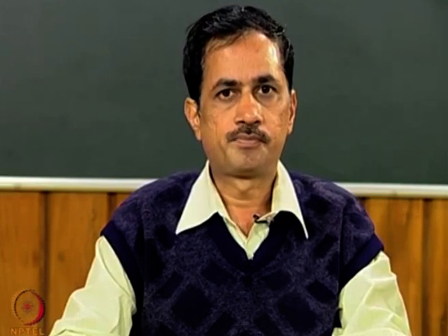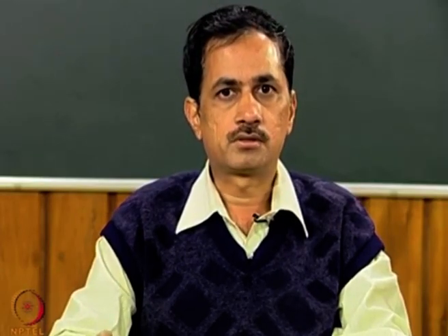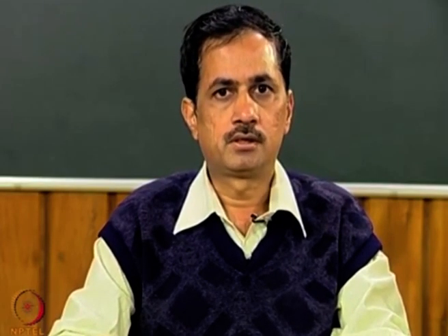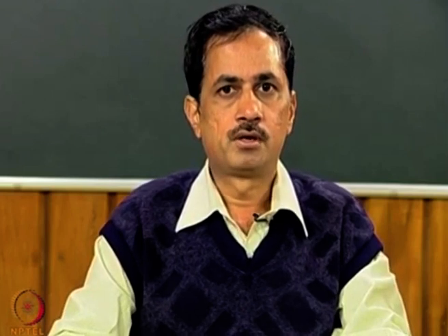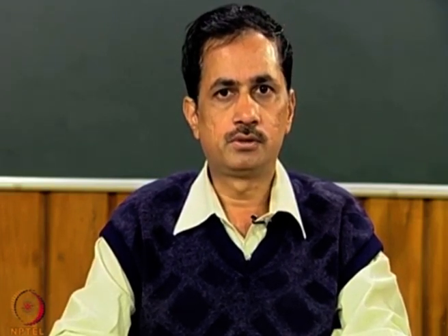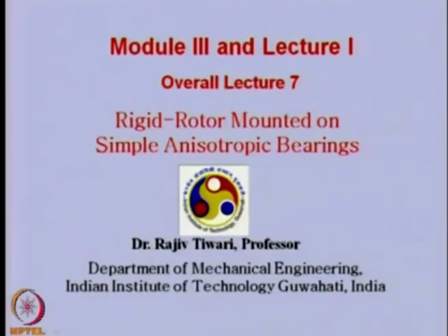For such analysis, obviously we need a different analysis as compared to the Jeffcott rotor model, and in the present lecture we will consider not only the flexibility of the bearing, but also the support or the pedestal flexibility, and how we can study the effect of this flexibility, especially on the critical speed of the shaft. Now, let us see the overview of the presentation.